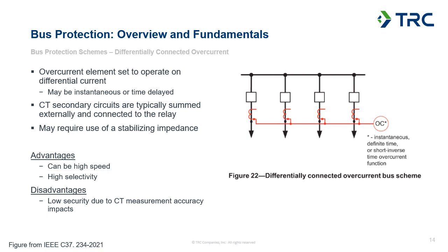If you start having currents that are too high or you've got too much of an impedance connected to the current transformer, or it's just underrated for the application, you'll start to see the output of the current transformer be reduced. So if you have that, and let's say your current transformer starts to saturate, which is what we call it when it no longer is reliably replicating the primary currents on the secondary side. So if one of your transformers starts to saturate and starts to put less secondary current out and has a higher error, that's going to drive a differential current being fed to that overcurrent element, because one of your CTs is putting out less current than it should, so the others that are putting out the full amount of current as expected aren't going to sum to zero anymore.